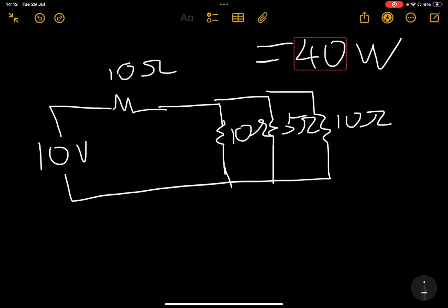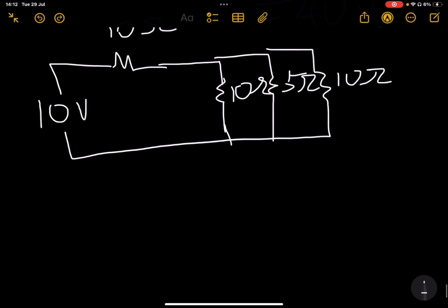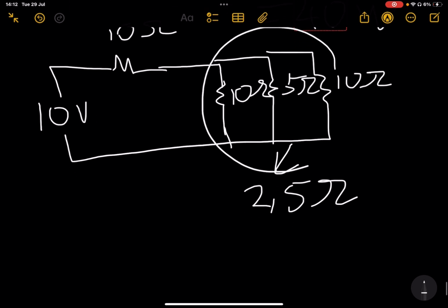Alright guys, just taking another look at a slight curveball in the equation. If I put in the series resistance with what we've already had, which is 3 in parallel, what will happen? Alright, what will happen to the circuit? Let's go through that. It'll change the resistance total seen by the battery. The resistance of the parallel part is equal to 2.5 ohms, which will not change. That is the equivalent series circuit of that, if we had to put it in the circuit. So obviously this whole mesh equates to 2.5 ohms.